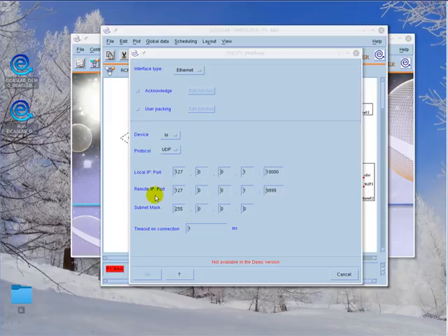Then, the local communication passes through the loopback network interface LO, which by default has IP address 127.0.0.1 and net mask value 255.0.0.0. The plant emulator has been scheduled in order to provide one measure each millisecond, so the thread in which the processor activities work should work every millisecond. The timeout is here set equal to 1 millisecond.